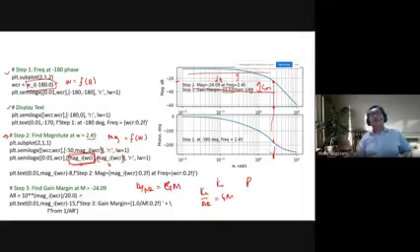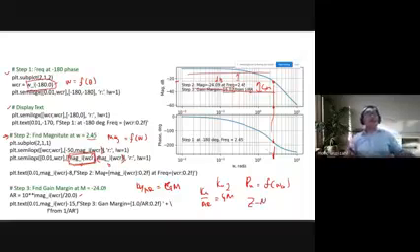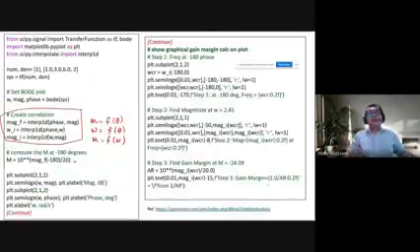And then you can use PU, a function of WC naught. Then you can get the controller for Ziegler-Nichols already. That's how you design the controller, if you proceed after the stability analysis. This is just to show in the graph nicely, so that you can present it in your report.